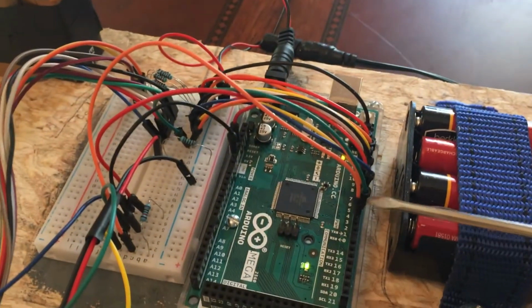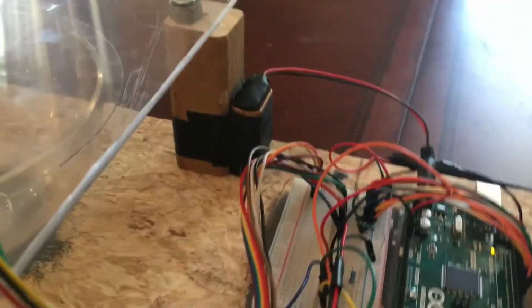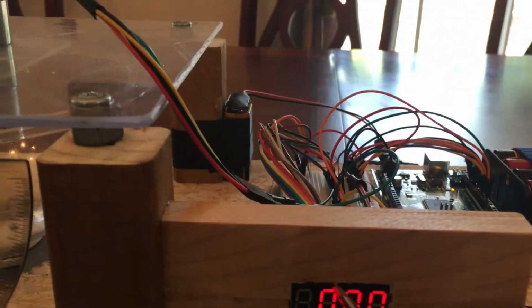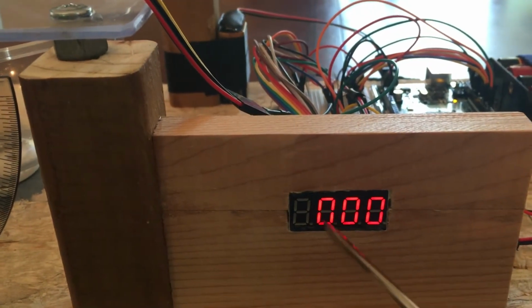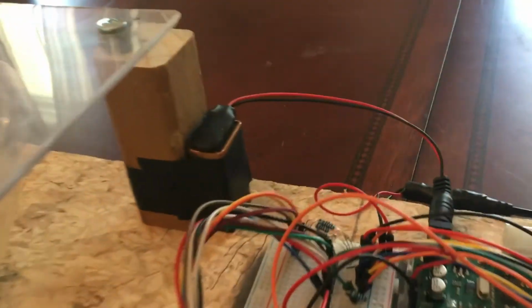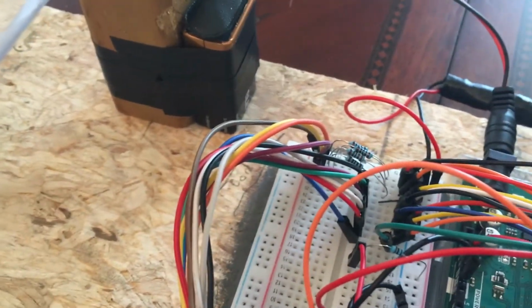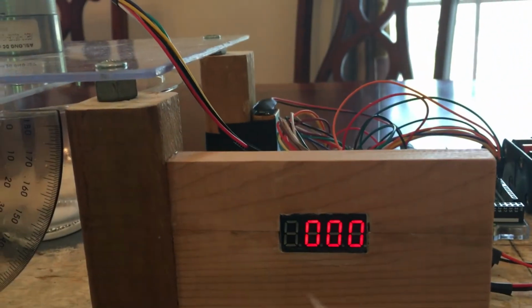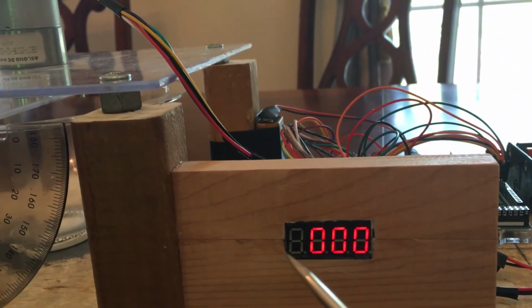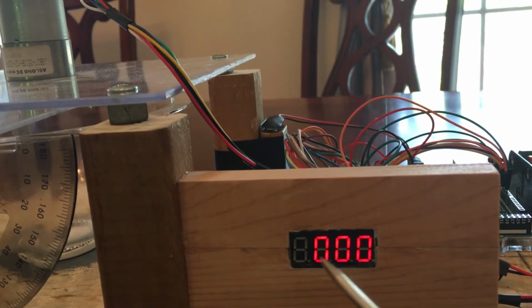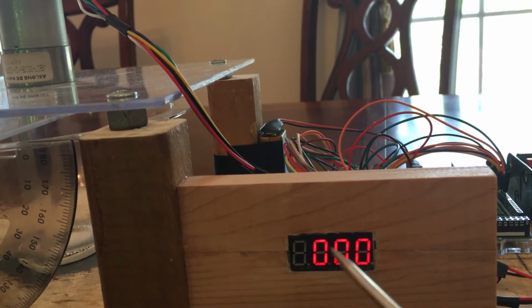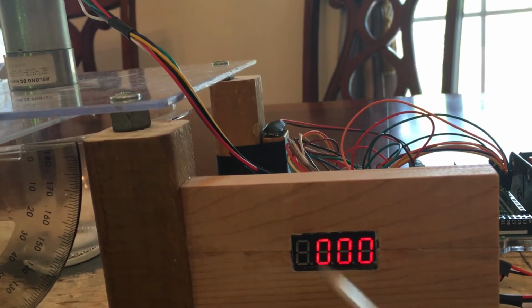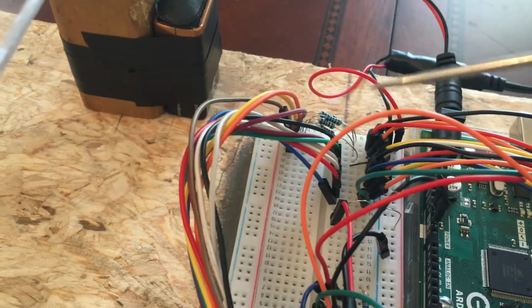Digital pins 3 through 9 are segment pins, which control each of the 7 segments you see here. Digital pins 10 through 13 are the common pins, or the digit pins, which control which digit is being displayed at what time. The display cannot actually display all 4 digits at once. It has to cycle through each of them at a very fast speed, which we've set to 1 millisecond. So these 4 pins control what digit is being used.